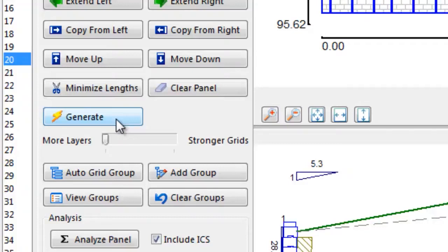However, the constructability of the wall should also be taken into consideration when generating a design. As a result, AnchorWall Software has provided a method to limit how tight geogrids can be spaced together. In other words, the designer may prefer to use a stronger geogrid placed every 18 inches vertically over having a weaker geogrid placed on every block all the way up the wall. This would be preferable from a constructability point of view, as well as probably being more economical.